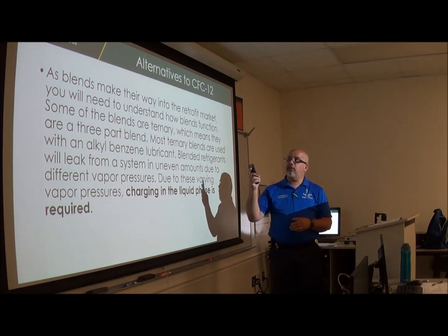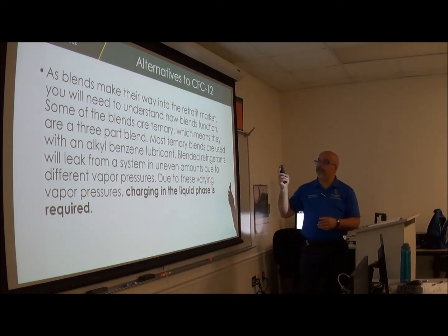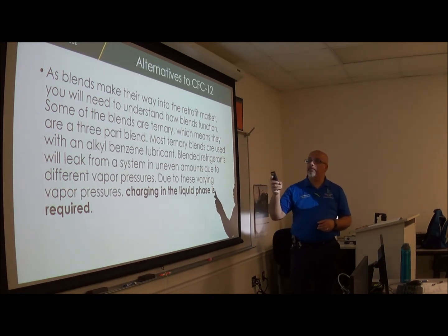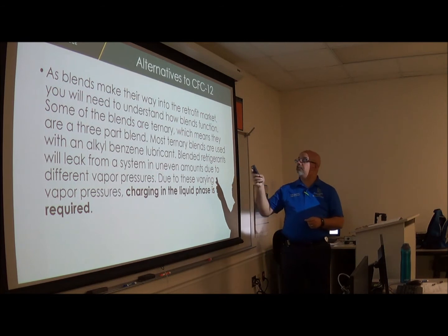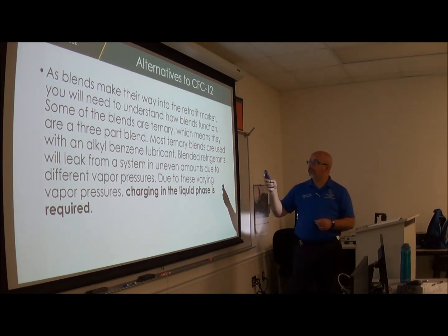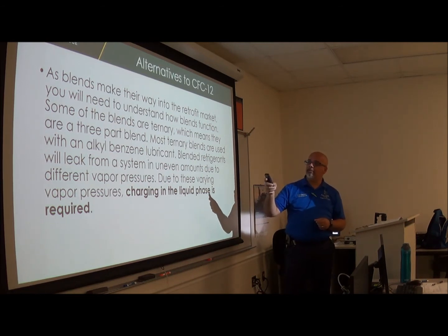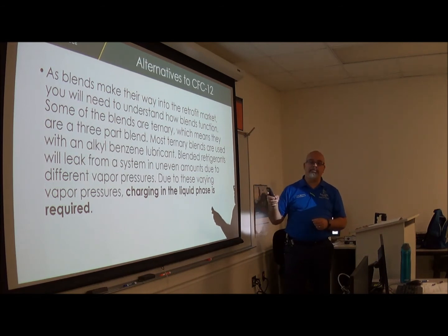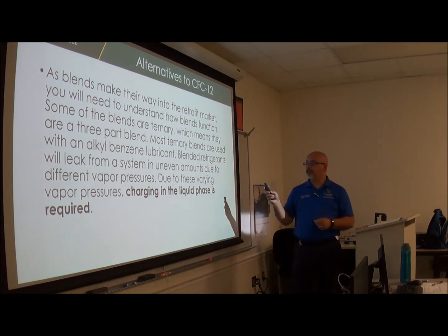As blends make their way into the retrofit market, you will need to understand how blends function. Some of the blends are ternary, which means they are a three-part blend. Most ternary blends are used with an alkyl benzene lubricant. Blended refrigerants will leak from a system in uneven amounts due to the different vapor pressures. Due to these varying vapor pressures, charging in the liquid phase is required.